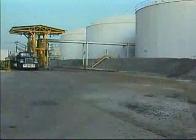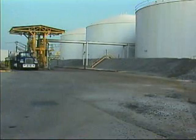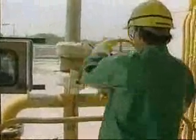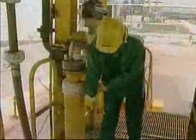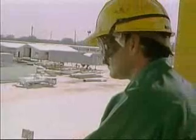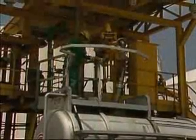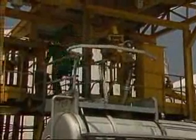The operator then double-checks the valve lineup to make sure that the product to be loaded is coming from the correct storage tank. If the lineup is correct, he opens the valve in the line from the storage tank, and then opens the valve in the product line leading to the tank truck. Finally, he starts the pump to begin the transfer. During loading, the operator watches for leaks or other abnormal conditions. He also checks the tank level to make sure that enough room is left to allow for thermal expansion.